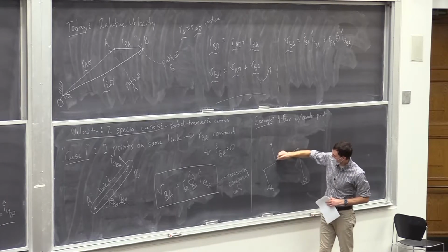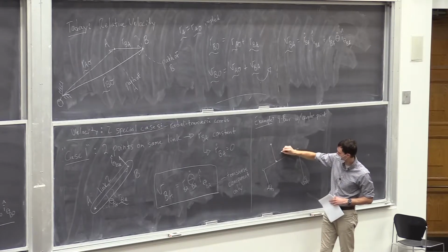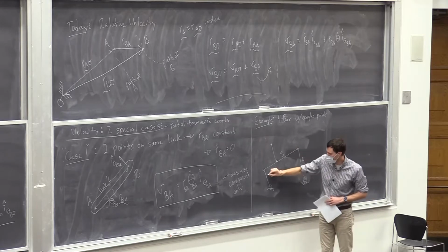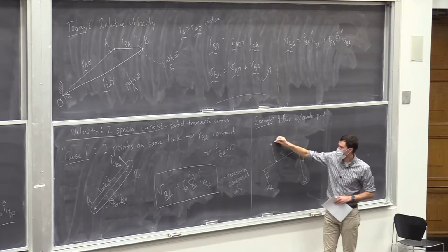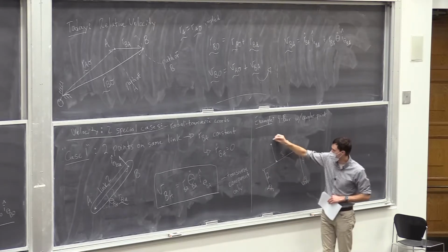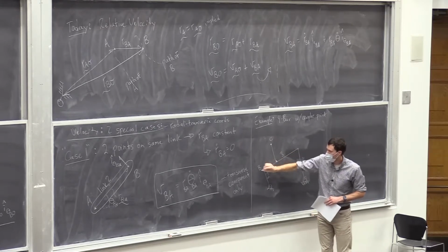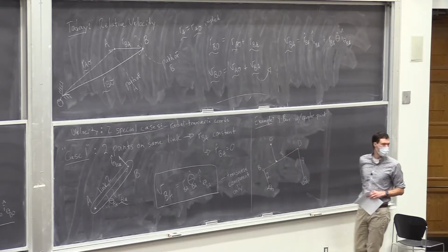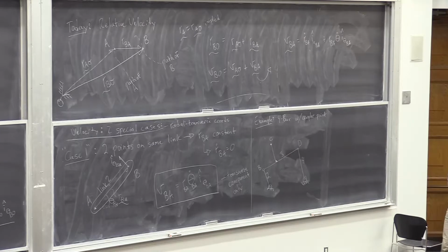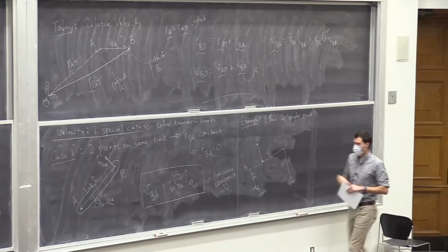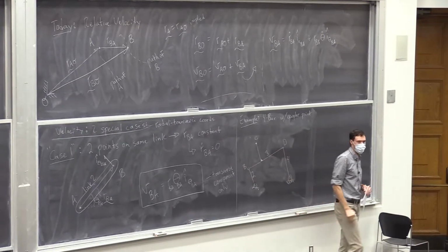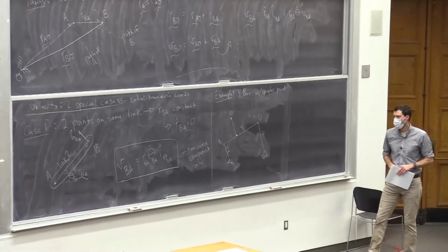And by coupler point, I mean link 3 here has an extension on it. So this is my extension point, and I'll call that point C out there. And these other pivots are B and D. Okay, so link 3 just has this extension attached to it. We've seen some 4-bars like that before.